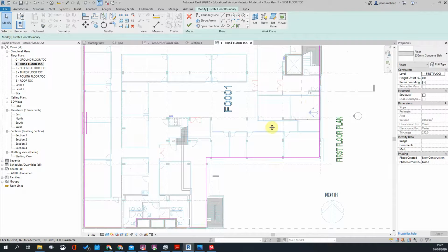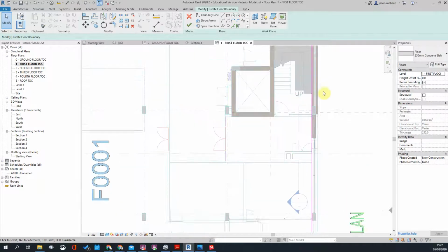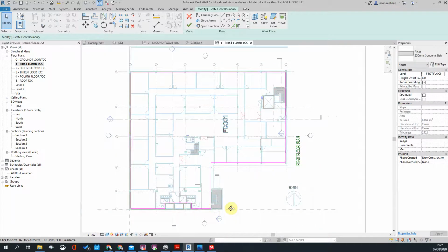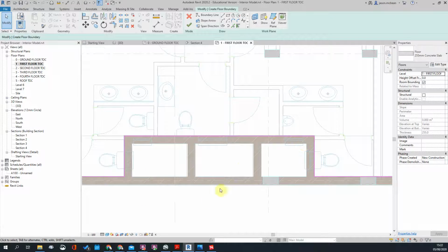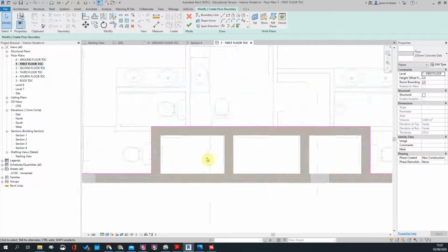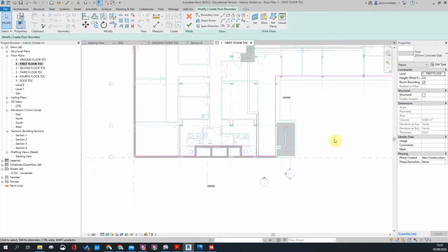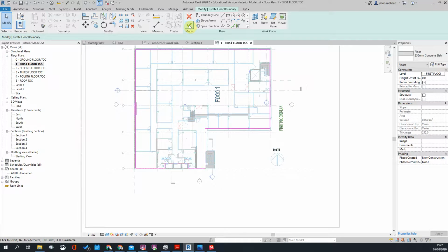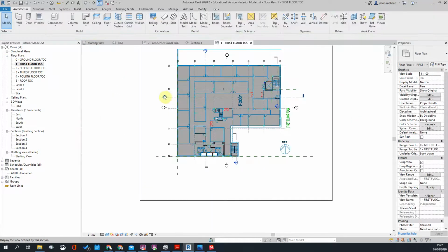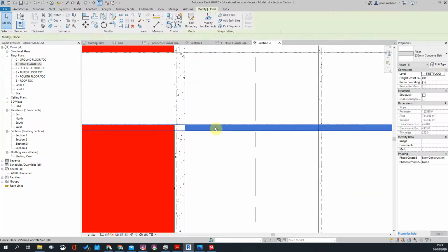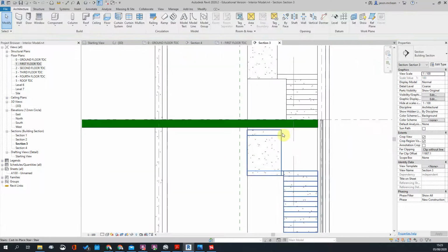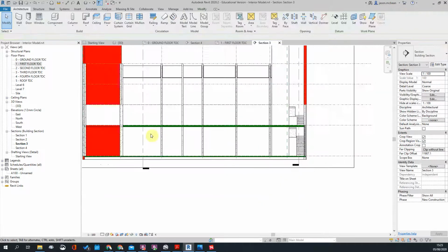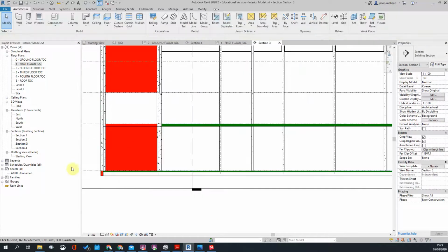Okay, so where the stairs go and the lift shafts go, there's some tools where we can either cut around the stair or we use a shaft. We create a shaft penetration. For example, where these openings are, we could have used a shaft, but I know for a fact that I don't have to use the shaft detail for that. But where the stairs start coming in, we'll need to start cutting away some of the slab. But for now, all I'm interested in is getting a floor slab in this area, so I can start seeing where I'm short on rises and treads and that kind of thing. So that's that in a nutshell. This floor slab is covered.